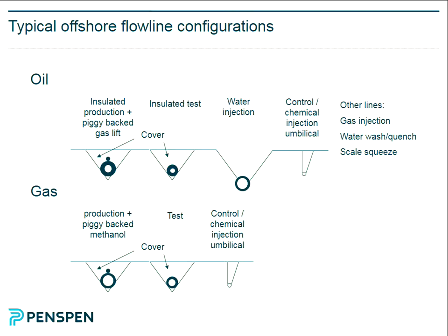So I would say typically in the North Sea and other fields around the world, you have water injection to maintain the reservoir pressure, and then you have gas lift to actually reduce the pressure drop in the wellbore. Because in a hydraulic system, if you consider going from the reservoir, the perforations in the bottom of the well tubing to the separator, sometimes the most pressure drop actually is in the well tubing. So if you think about multi-phase flow, it's not just in the pipeline, it's actually in the well tubing. And with deep reservoirs, you might find that's where most of your pressure drop and your temperature drop takes place. So gas lift.